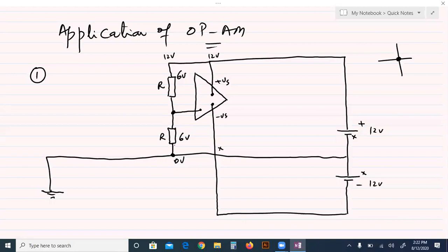So which voltage will go as input to the operational amplifier? The voltage across the resistor which is connected with the earth. So this is connected with the earth, so the voltage across it is actually the non-inverting input voltage, because this resistor is connected with earth. Very, very important. So at this instant, the voltage input at this non-inverting terminal is 6.